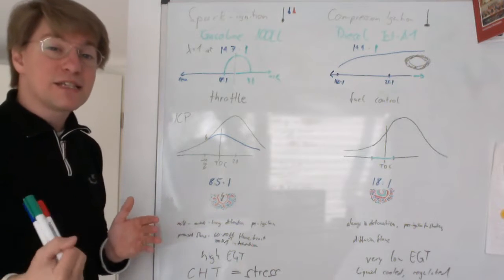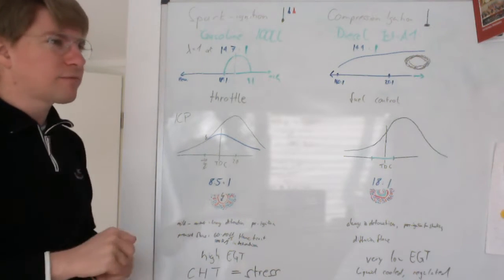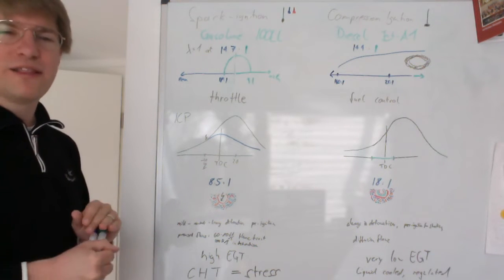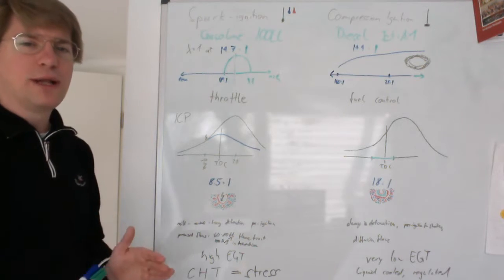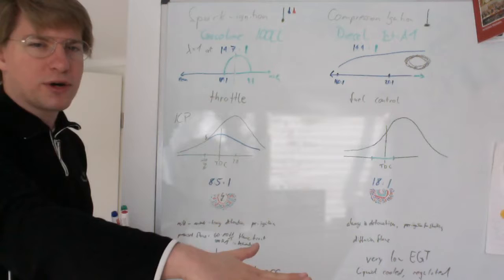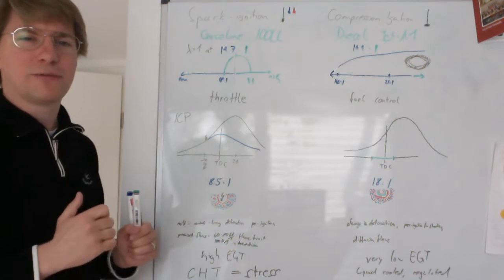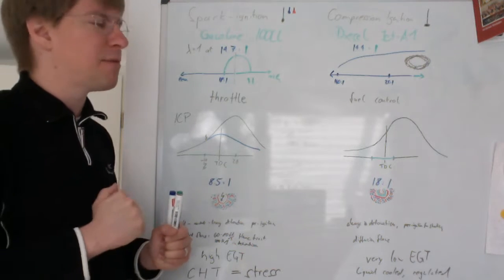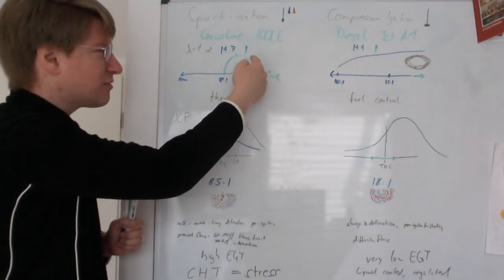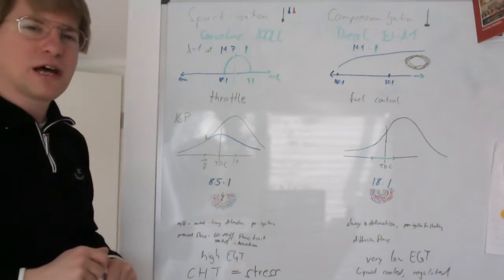Of course, it gets less efficient because we are burning more fuel. The engine will run cooler because we're not burning all the fuel. The combustion itself will be slower, so this will lead to lower exhaust gas temperatures and lower cylinder head temperatures, which is why we want to run there for takeoff when we're extracting the absolute maximum amount of power from our engine. And if we go even further to the rich side, at some point the curve begins to fall precipitously and goes down to 0.